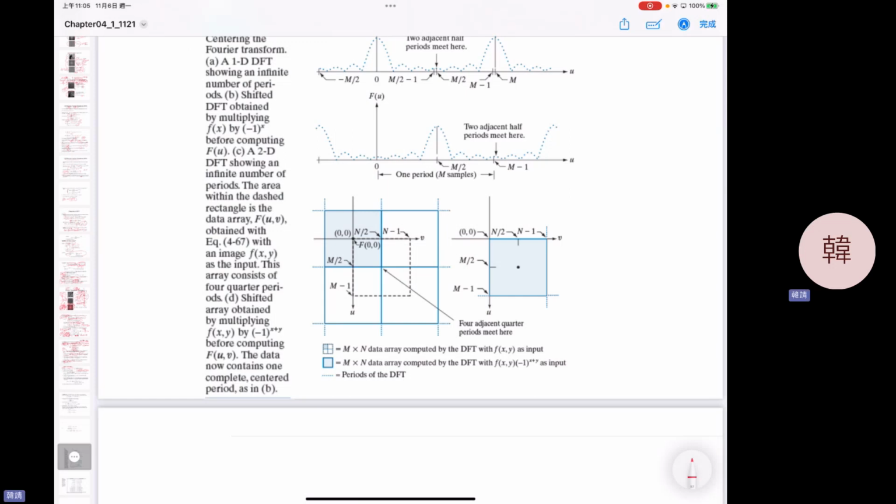The positive and negative sign, and compute the result of multiplying the phase angle by 0.25. Okay, so if you try to change the scaling factor, -1 is 180 degrees, so you can expect that. But unfortunately, if you multiply by 0.25, what do you expect? You have to calculate the cosine of 0.25 times the arctangent theta, and the result looks like this. Nothing there. It becomes a disaster. So be careful, again, the phase angle is important.